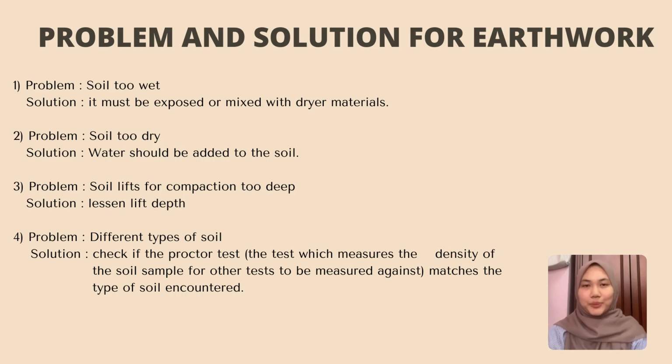Then, we proceed to the problem and solution for the earthwork. Earthwork is the process of excavating, transporting, and compacting the earth's surface at a similar location. Earthwork is mostly done during the early stage of construction. Some of the most typical problems found in the earth excavation and site grading are improper compaction, incorrect final elevations, and working beyond the designated area to be disturbed. The following are some examples of earthwork problems and their solutions.